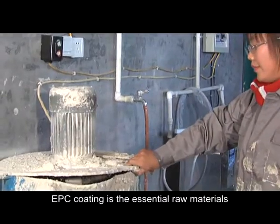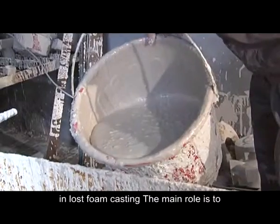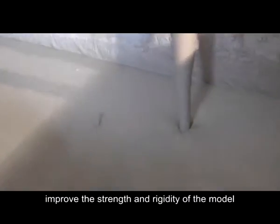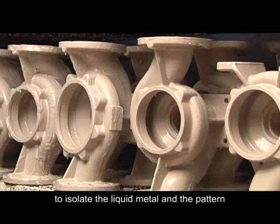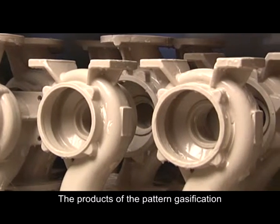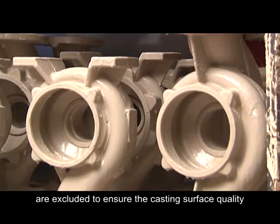EPC coating is an essential raw material in lost foam casting. The main role is to improve the strength and rigidity of the model, to prevent damage or deformation, and to isolate the liquid metal and the pattern. The products of the pattern gasification are excluded to ensure the casting surface quality.